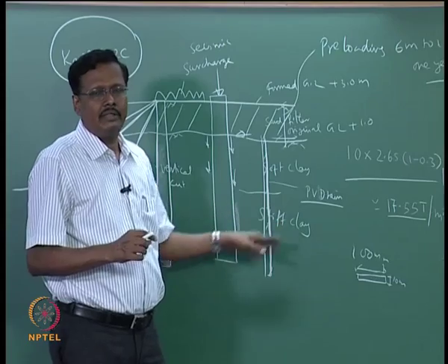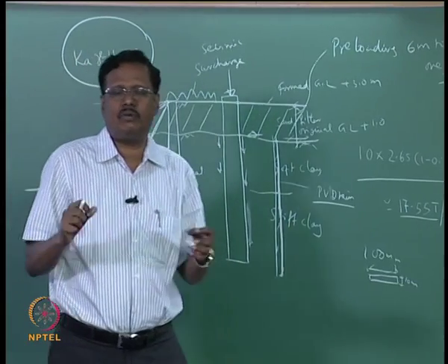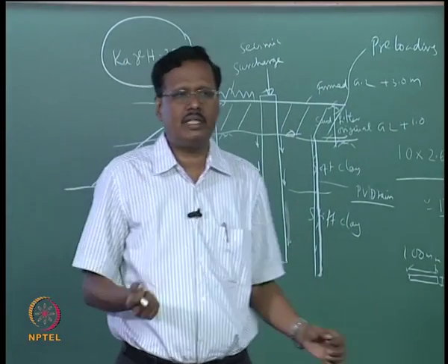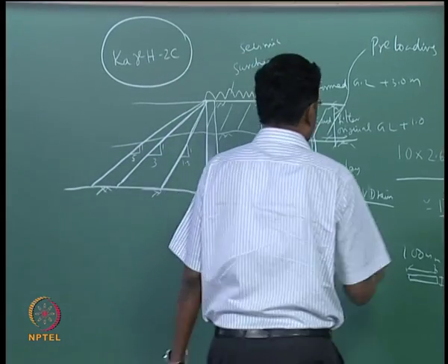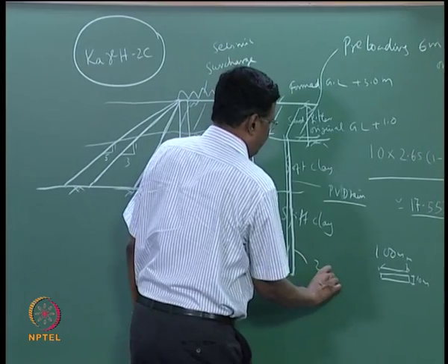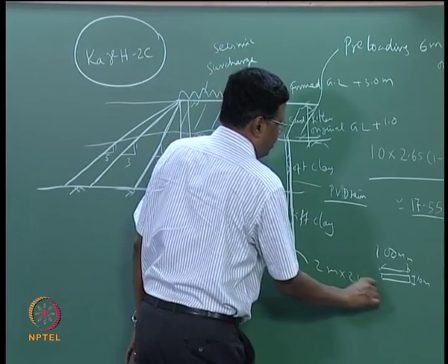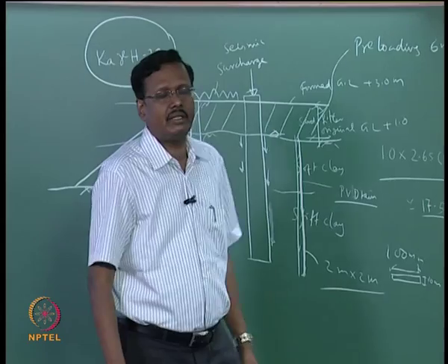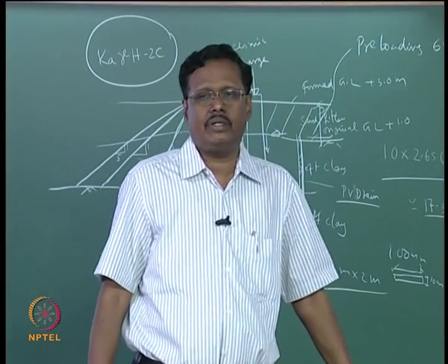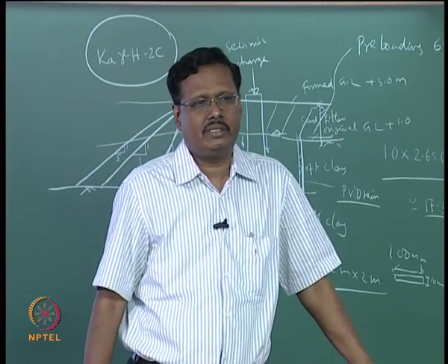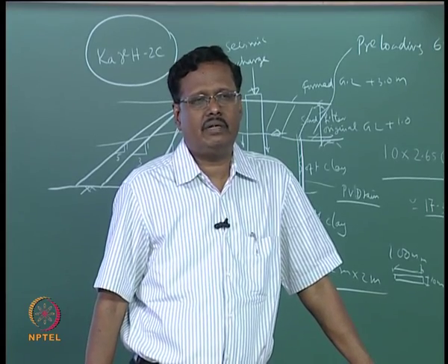There should be a place for the water to come out of the soil, we are accelerating that. This will be done in a square pattern, maybe a 2 meter by 2 meter grid. This is the most economical method of increasing the bearing capacity of the soil or improving the ground treatment. This is done in many places, it is not very expensive also.